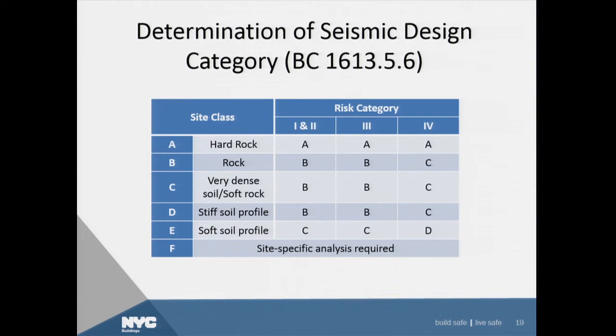Now, again, seismic design category, this is something that's just going to vary based on your site profile and your occupancy, the risk category. Here's just a simple breakdown of what seismic design categories you might get depending on the site class and the risk category.